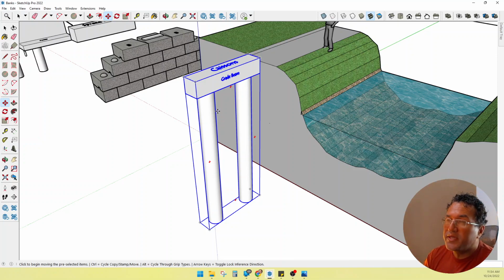There's a big hose that goes from the grade, from the top of the abutment all the way down to the bottom, and they pump it to the bottom and fill it up slowly. And you hope that there's no water. You hope you didn't slough off. There's so many things that can go wrong, and the costs just go way up when it comes to caissons. But they are very popular on government jobs because obviously they don't have to worry about such a large budget.